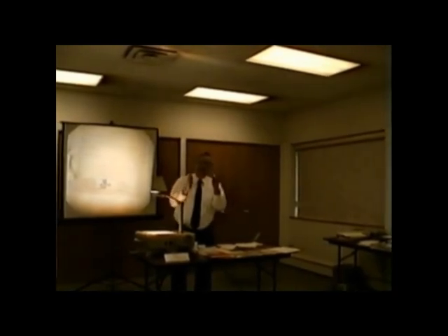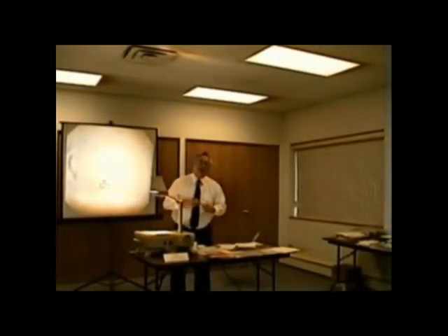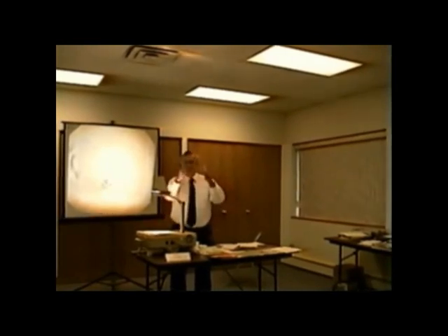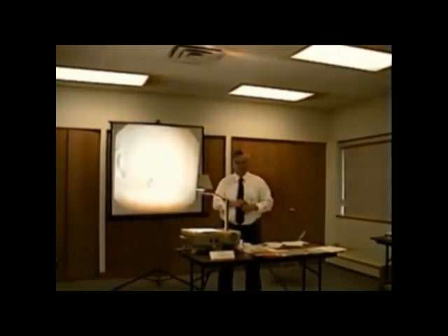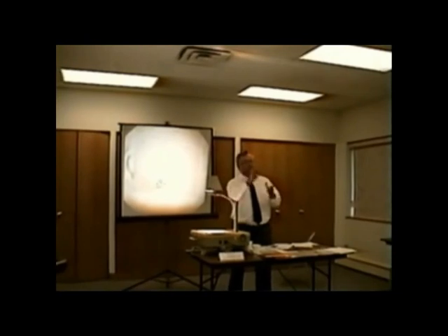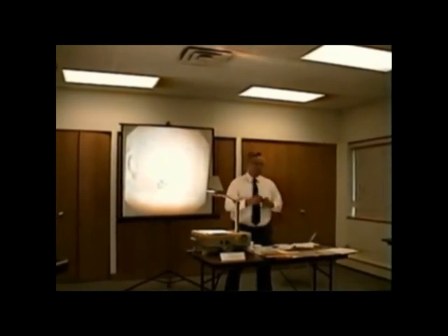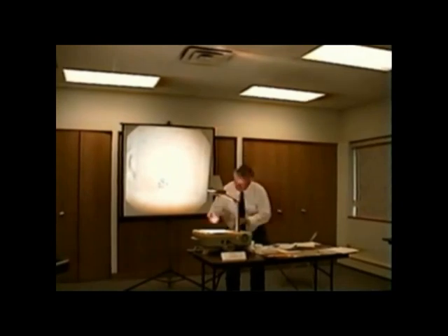So we got 118.6. Now, ladies and gentlemen, if it's the control voltage that's being supplied by 118.6, we just may have a transformer that is a 24 volt transformer with 120 volt supply. So we got a little bit less than 120 volt. So we would expect that our low voltage would be a little bit less than 24, just a little bit. So Herb, what do you think we could put down for a little bit less than 24 with a decimal? 22.9. Perfect. 22.9. So it all relates.